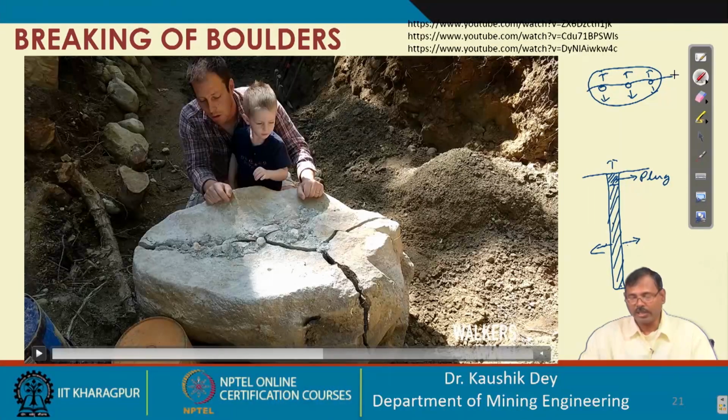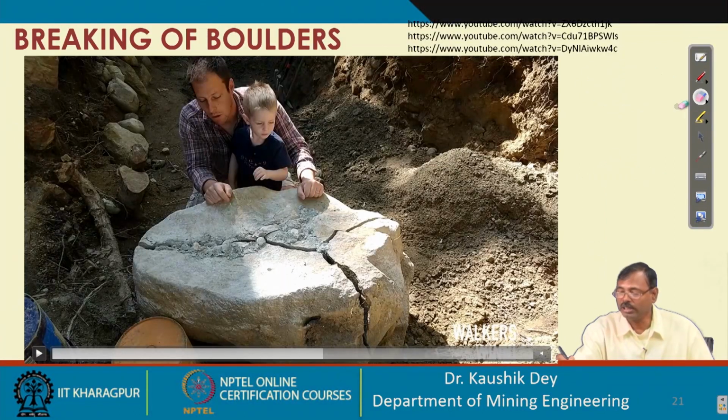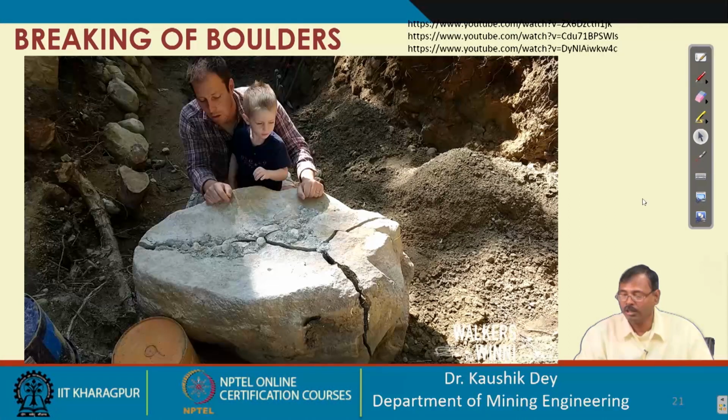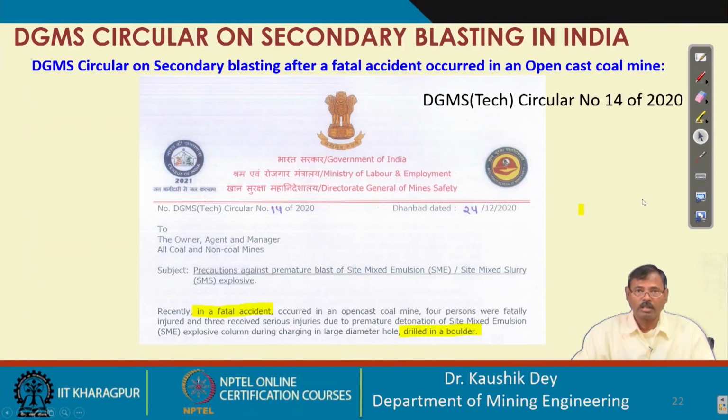Only the fact is that this cement is a little bit costly, and it takes a long duration for fracturing. It takes almost 6 to 12 hours for generation of cracks in the boulder. So, it takes time for fracturing, and that is another drawback of the system. Otherwise, this system is very good and applicable to any place, though it is a little bit costly arrangement. So, this is more or less about the boulder blasting.